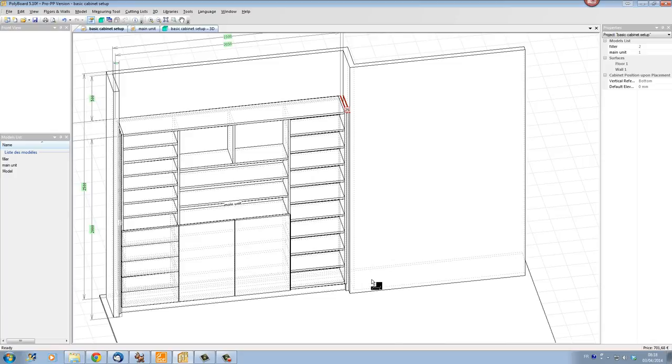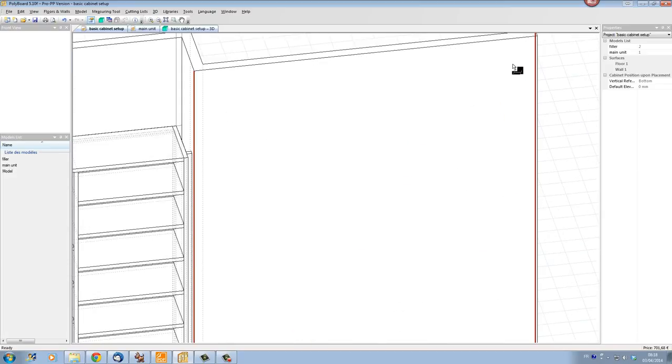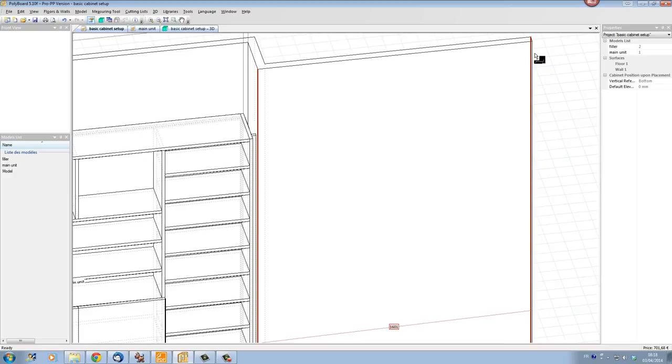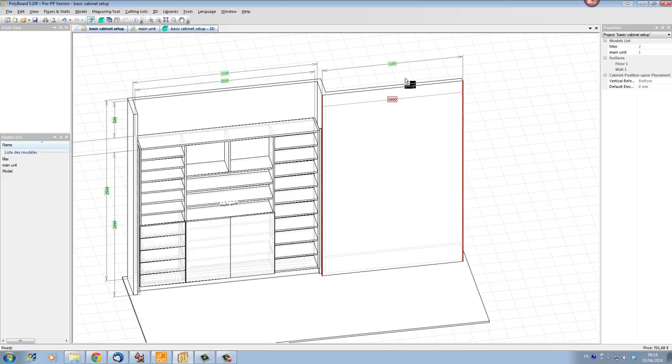For instance, if I need to adapt a cabinet to fit here along this particular wall section here, I will click here to here. Well, be careful because here I'm on the back edge, okay? So what I want is, be careful, I'm on the front edge here. Front edge, clicking up here, 160. Let's put that as a permanent dimension here, and we'll get 160 up here.